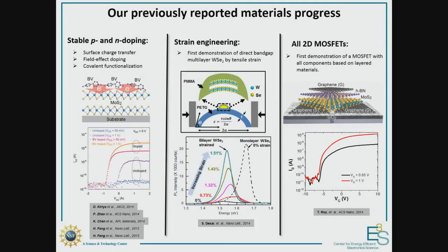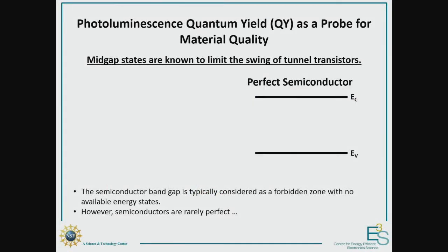It's very similar to germanium. You can do the same thing with germanium. And we have demonstrated this with these chalcogenides as well. We've also looked at how we can build transistors where all the components, the source, drain, the channel, gate dielectric, and the gate are made of layered material. So we have figured out ways to transfer these and to build transistors where really all the junctions are based on these van der Waals interactions.